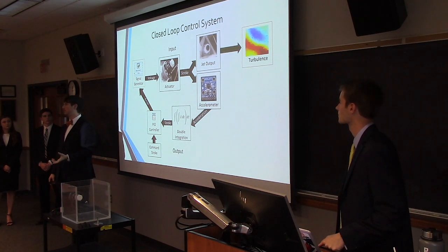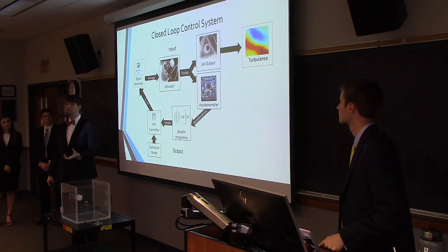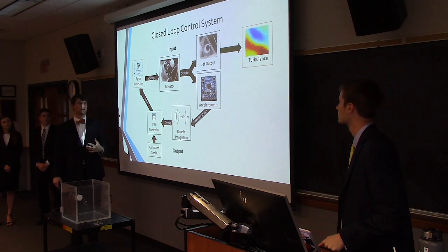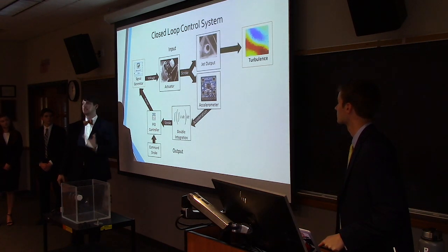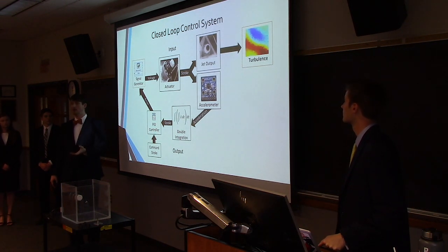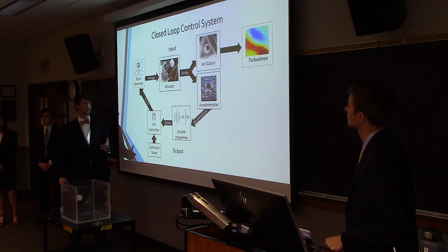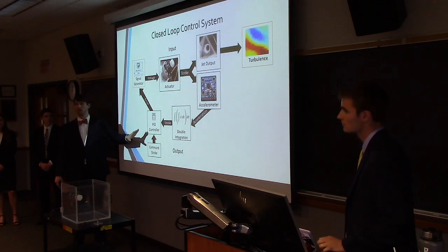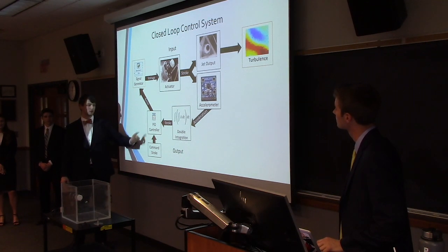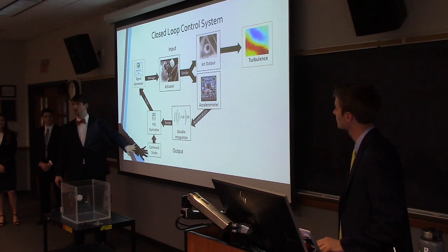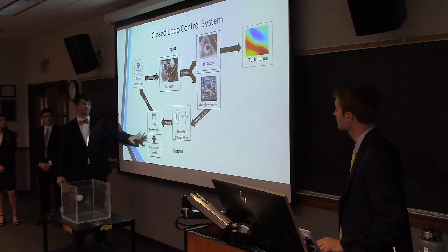Accelerometers only measure the acceleration, but we know from physics that if we integrate the acceleration twice, we're able to get the actual stroke and the displacement that the speaker is doing. So with that, we then put that through what's called a PID controller. All this does is compare the stroke to a command stroke of what we're trying to target. If the stroke is too high, it's going to reduce